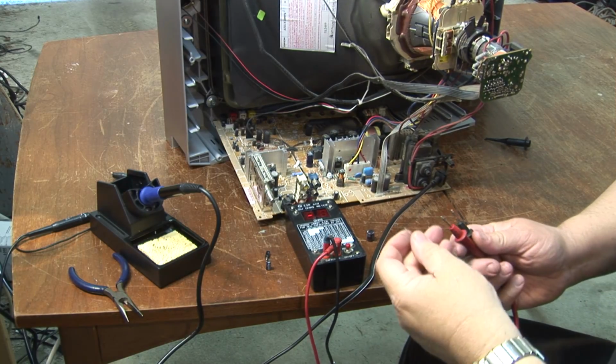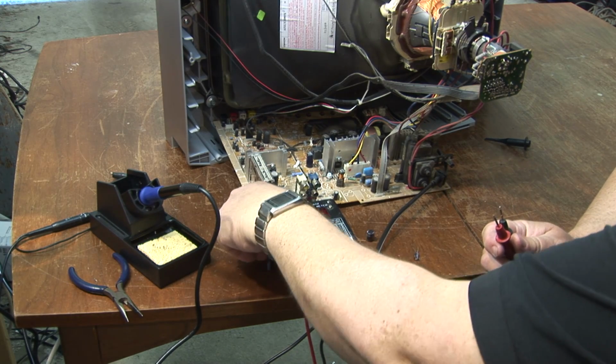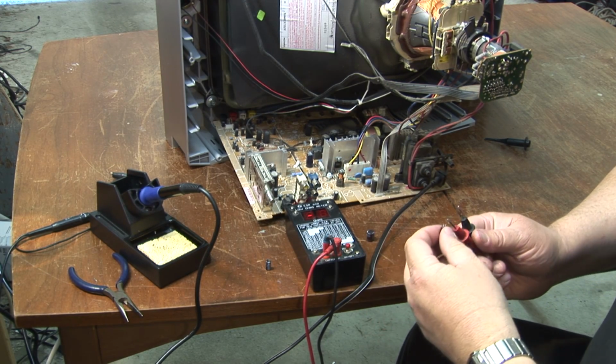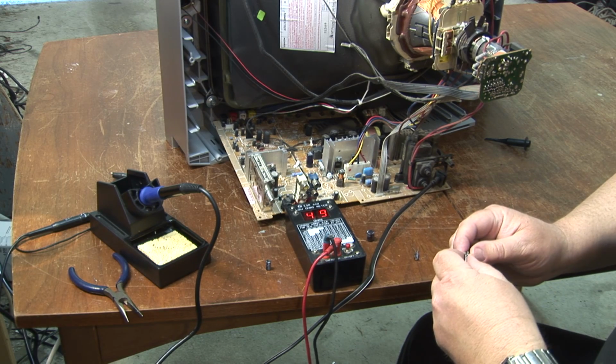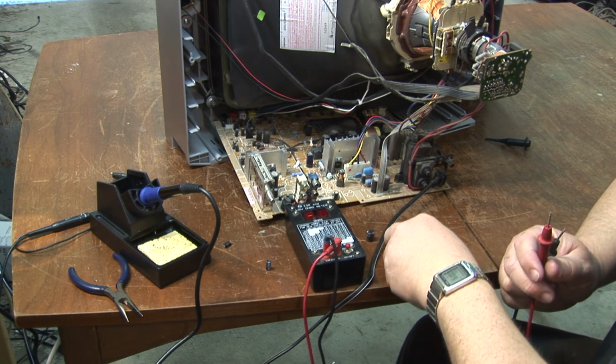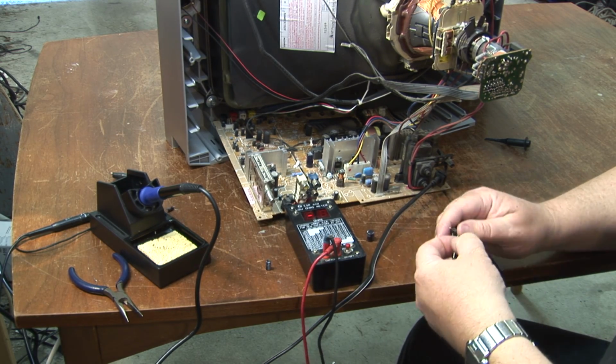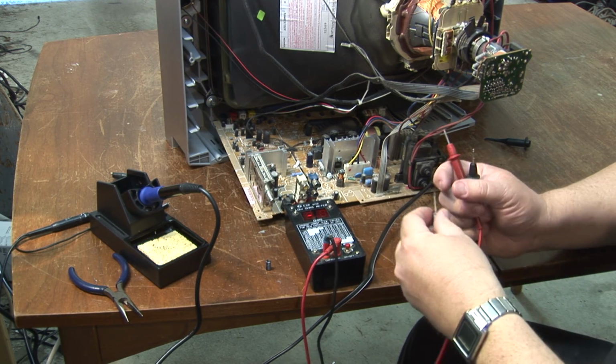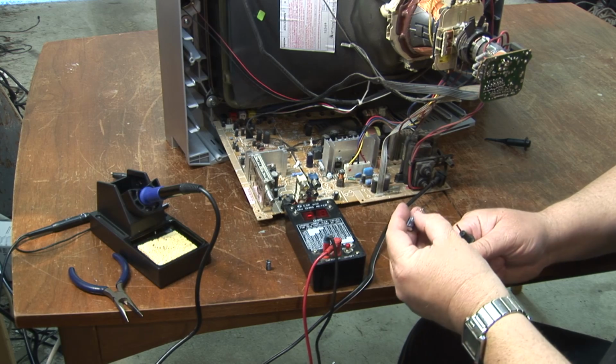Now remember, I showed you the 1 microfarad before, the old one here, even though it says worst case would be about between 14 and 16 ohms, and this one here is measuring up at 4.9. But here's a new one. Okay, a new one's 3, so it is starting to go a little higher. Here's the 100. The other one was measuring open.